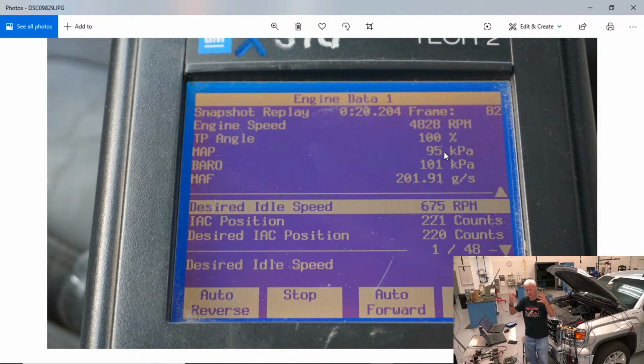and then when you start the engine up and pull that low pressure down, you create a vacuum in the intake manifold that takes 20 inches of vacuum away, and then you're left in the intake manifold with 10 inches of mercury. That's the absolute pressure. That's not gauge pressure. That's how much actual pressure you have in there. If you can pull all of that out, if you've got a vacuum pump or something like that, and you can pull all the